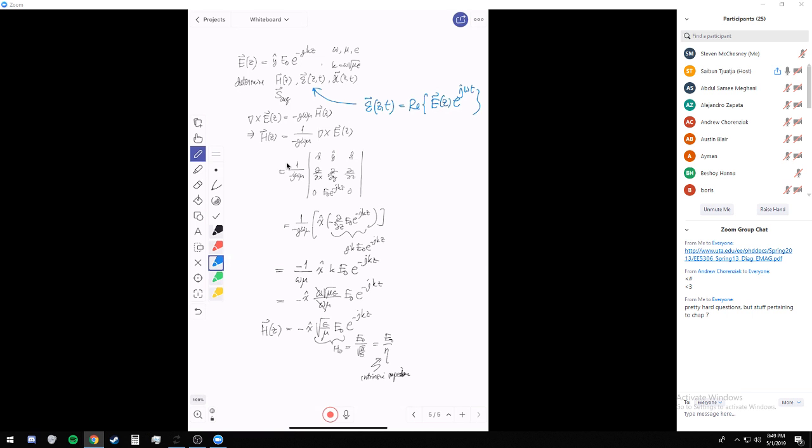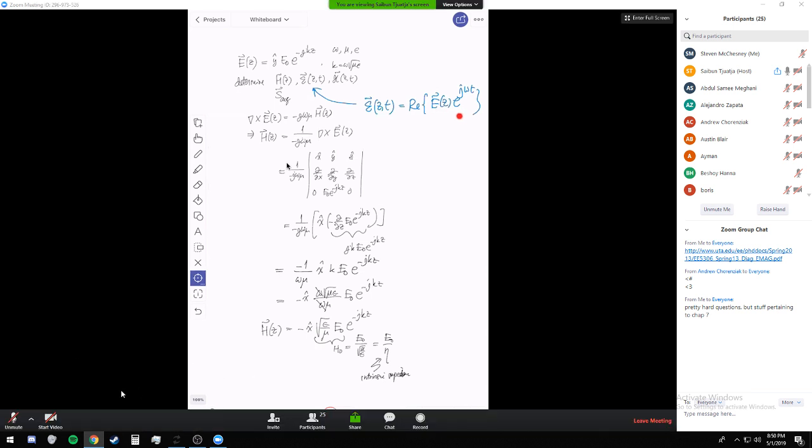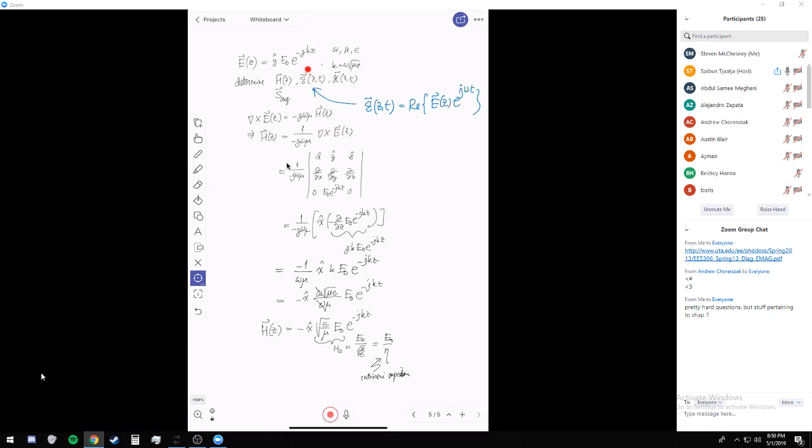Okay, instead of solving it, who doesn't know how to take care of this part? I think the book has some examples and samples of how to solve this. Make sure you know how to do this. And the key thing here is this. For electrical engineering, we use e to the j omega t. Again, if you go to science, physics, chemistry, they are most likely using e to the minus j omega t. So all the formulations that they develop in those books or reports, the result is somehow the conjugate of what we have.